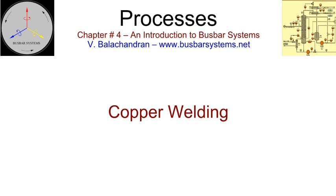Copper laminates were fabricated like aluminium laminates. Solid tabs were welded to a stack of laminates. With the development of resistance weld technology, which gives much better results, this method of making laminates has now become obsolete. However, site welding of laminates to terminals in arc furnaces and similar applications is still being carried out. TIG welding and MIG welding are adopted for the welding of copper.